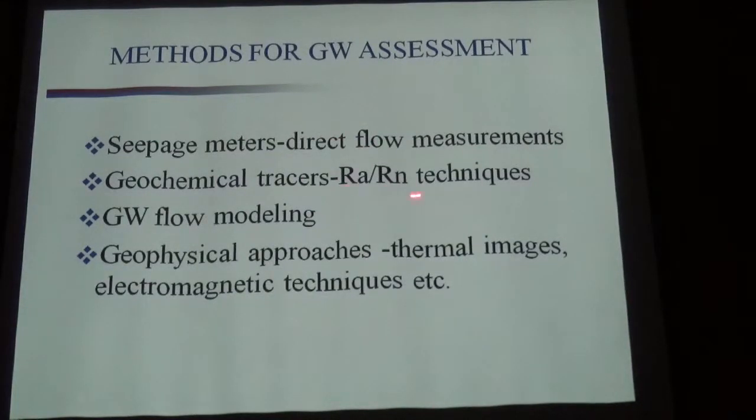Groundwater is very highly enriched in these because it's been so long in contact with the aquifer. It accumulates all these radioisotopes, while surface water doesn't have the source, so we would expect very low concentration. So if we see some signal of these isotopes in surface water, that means there must be a source, and it's most likely groundwater.